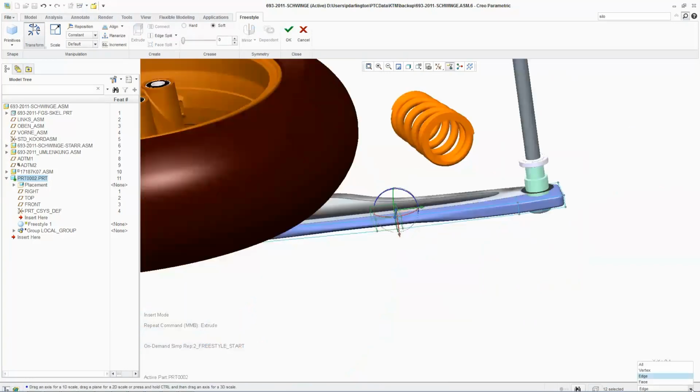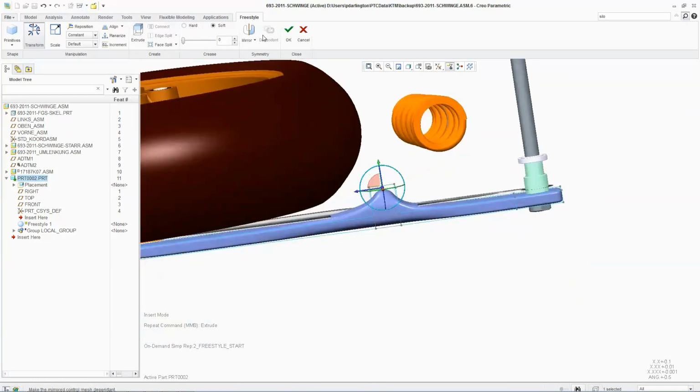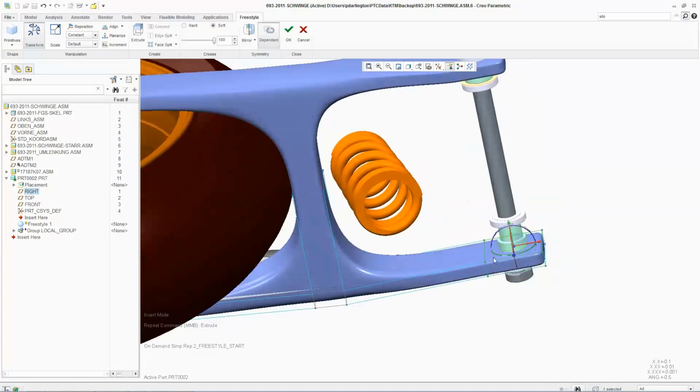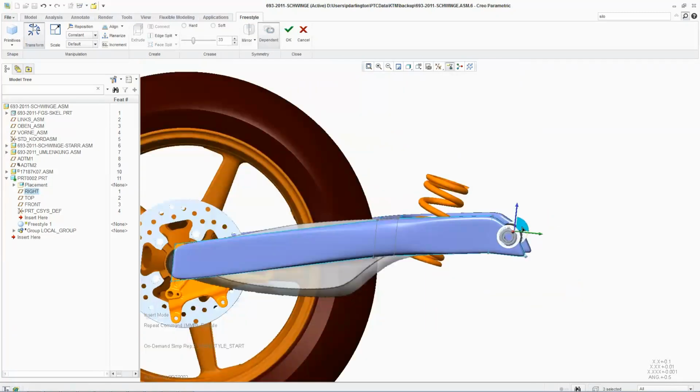So it's very easy to add in more sections, to move certain pieces around, add increases. And what I'm going to do now is take this and maybe grab a certain vertex and just pull it out in a direction. If I want to make sure that's going over into the middle, just quick menu, add in a new piece there, bring it towards the center. And even if I wanted to mirror that across, I could do that as well. It means that whenever I make changes to one side of the swing arm, the other one's going to update as well. So with that, I really only need to work with half of the design, and the system will automatically build out the other half for us.